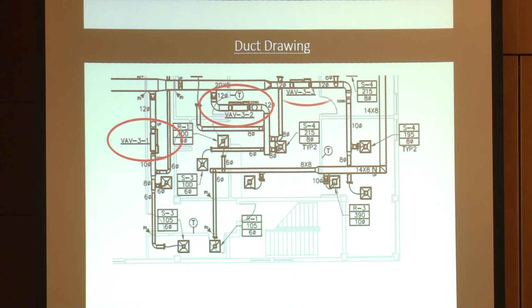Now, a lot of jobs these days have variable air volume boxes. Do you use a lot of VAV boxes here? I don't know. Do you see them a lot or no? We use them almost everywhere, because it's great, because they go from a low CFM to a high CFM, depending on the temperature of the room. So it's really forgiving for a design engineer. He can have a lot of leeway to get the temperature he wants in the room using different flows. So we have a lot of VAV boxes, and we do a lot of this.